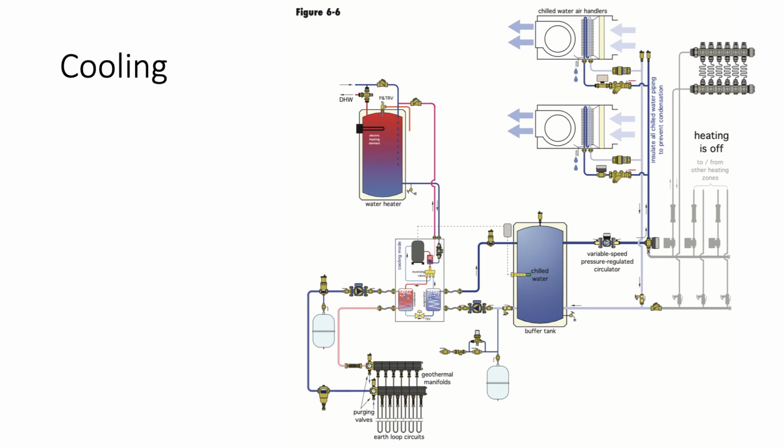Figure 6-6 shows the use of the ground source heat pump system as a cooling medium. The buffer tank is obviously blue, showing cold water. The cold water is sent up through fan coil units where it recovers sensible and latent energy. It is important that all pipes connected to a chilled water system be vapor sealed to avoid the production of condensate around pumps, valves, etc.